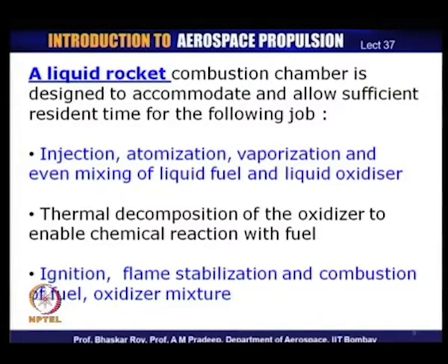So, the job here, with reference to, let us say, the jet engines, where the fuel was injected into the combustion chamber into air, and there only one fuel is to be injected, atomized, vaporized and mixed with the air. Here two fuels, that is the fuel and the oxidizer, need to be injected, atomized, vaporized and then mixed in correct proportion with respect to each other before the combustion can take place. So, these are prerequisites before the combustion can actually take place.